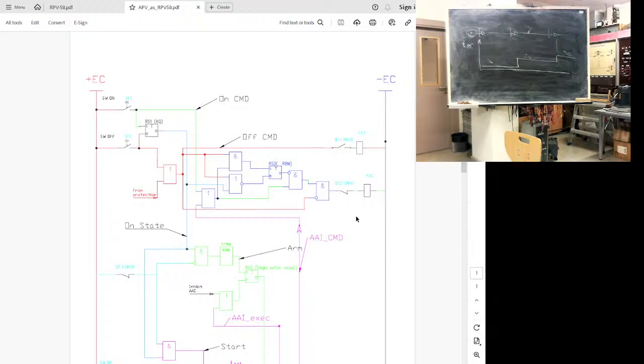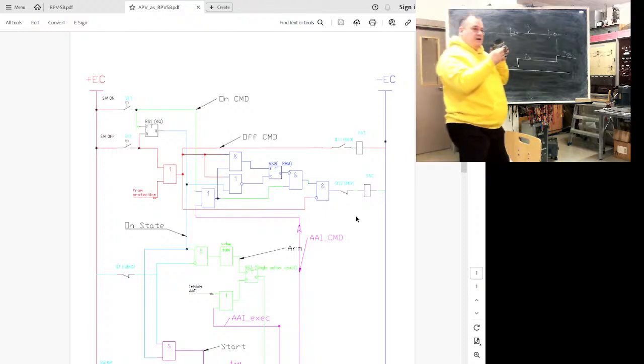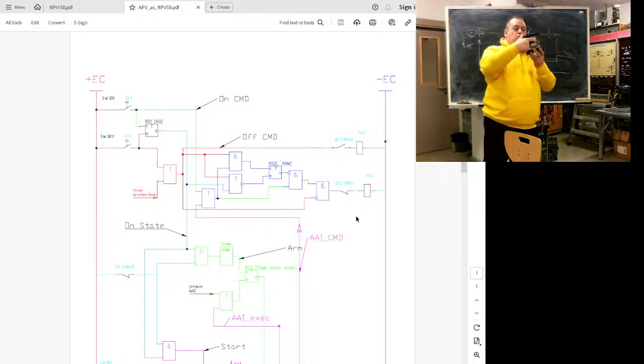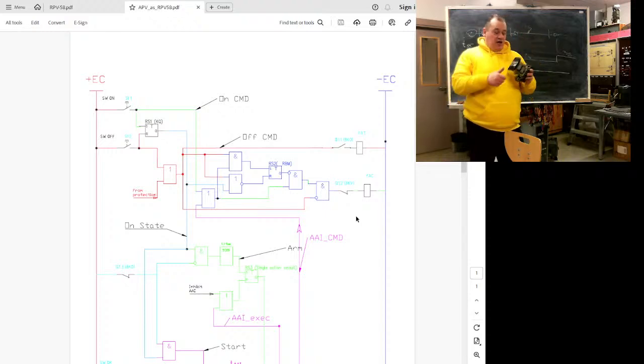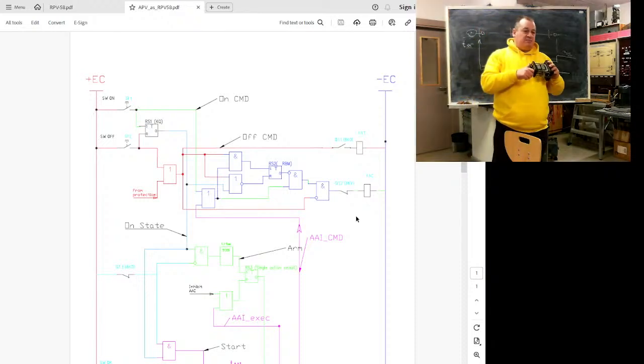Here it is. I'm getting cold. It's on a visible. Here it is. Trigger relay. Two position relay. It has two coils. If you send voltage to one, it switches and stays in this position. If you send voltage to another one, it switches and remains in this position. Actually, it's a memory for 1 bit.